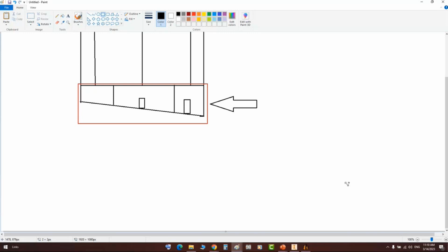Okay. So using the technique of adding an imaginary part, this is like a mandatory way that enables us to add the parts as a child. Yes, but if you would like to add a part to a shell or head or cone, you can do that easily by selecting the head, and after that adding the attachment.